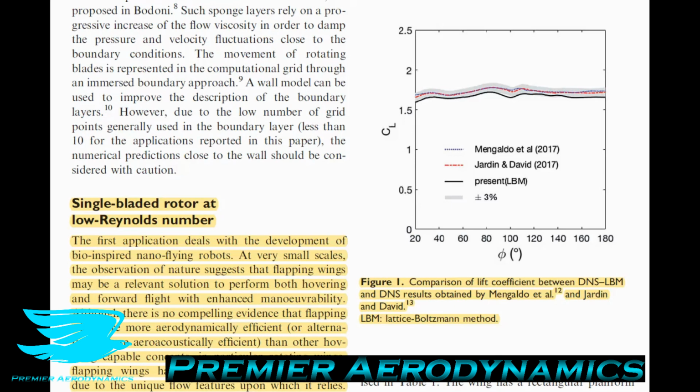One reason that I can think of, actually there are 2 reasons. One of the major reasons is that you don't have the mesh resolution ability with the Lattice Boltzmann approach. So what that means is to get finer resolution around the wing, you need to make the entire domain finer. That's a major limitation. Whereas with CFD, with the Navier-Stokes approach, you can just specify different resolution areas so you can refine near the wing a bit more. That's very beneficial.